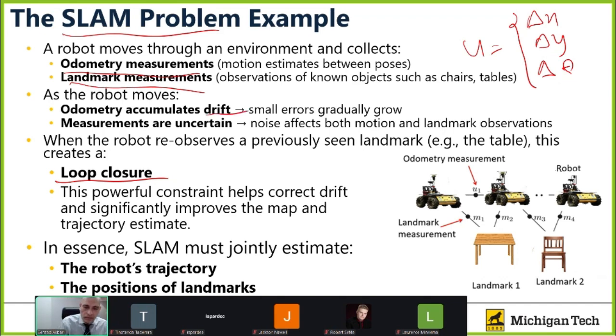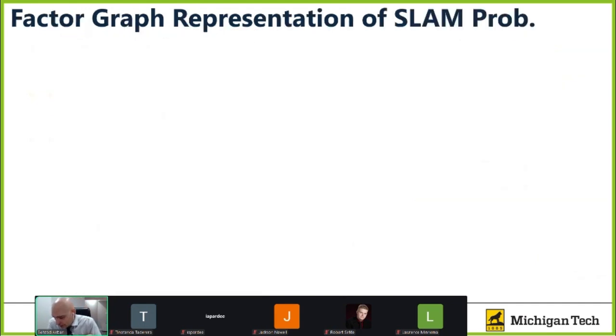When the robot moves, it adds new error, and after multiple steps the position that you have is not really the real position. How can we fix it? SLAM can fix it with loop closure. You just need to add another factor called a loop factor.